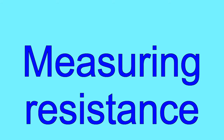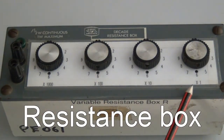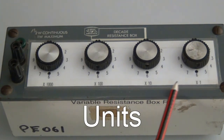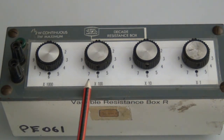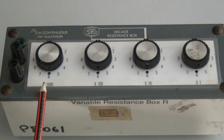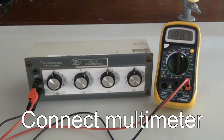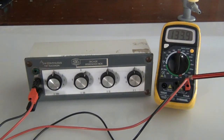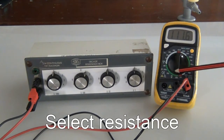We now measure resistance. This is called a resistance box with knobs representing units, tens, hundreds, and thousands. We can select any value of resistance. We connect the multimeter and we use the COM and the right hand side terminal.